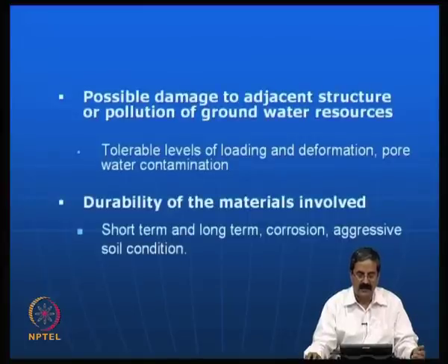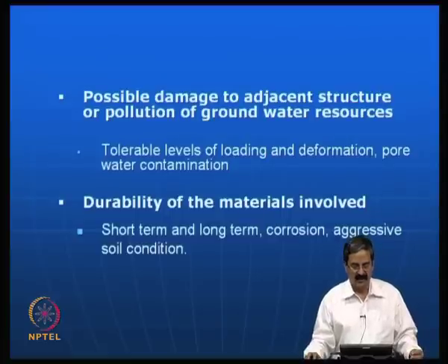Then when you are trying to use a ground improvement technique, you should also understand that, for example, you have an apartment and next to that you want to construct another apartment. If you start excavation next to the apartment, the owner will come and sue you, because the moment you start excavation, there will be some cracks in buildings and there will be a problem. So, one should understand what are the tolerable levels of loading and deformation. For example, you know about the concept of differential settlements and total settlements, right.